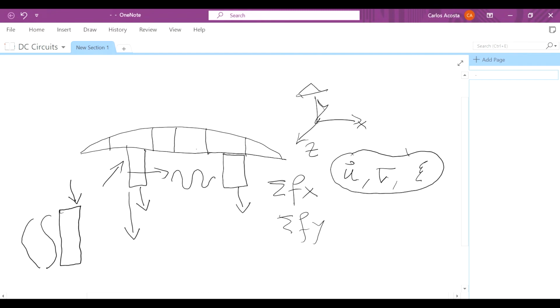But some other times when you have a complicated system, you don't have the exact solution. That's when you use a numerical approximation, a numerical solution that will tell you approximately what the deformation will be. And then, of course, engineering practice is that since it's an approximated solution, you oversize your system, you make it stronger by 15, 20%, so that the error of the solution is compensated by the over design of your system. Okay.